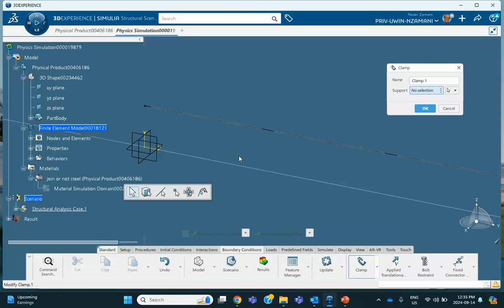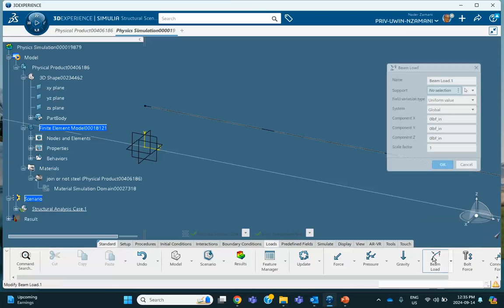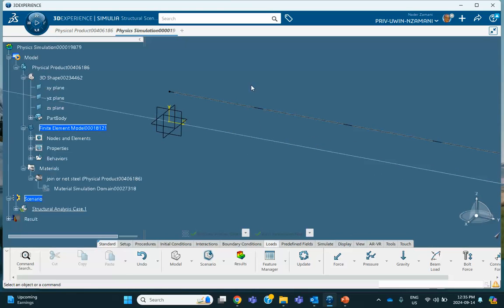So what I can do is to put it on a group. So let me cancel that. Okay. By the way, before I do this, let me show you that even if I wanted to do the load being met on this line, it won't take it. But I can put it on a group. So cancel that. We have to go and create groups. Okay. Where do we create groups? It's not in the create scenario. It's in the where we mesh.